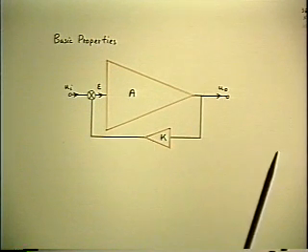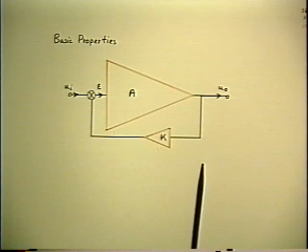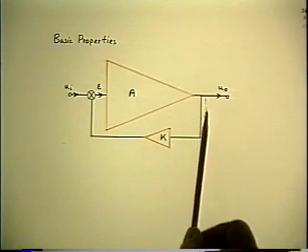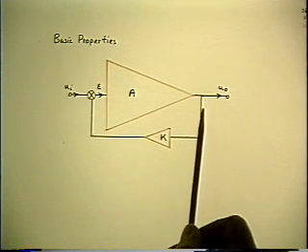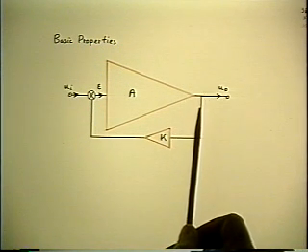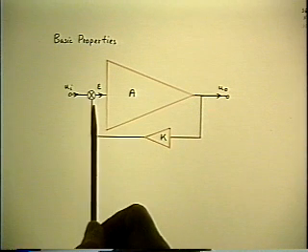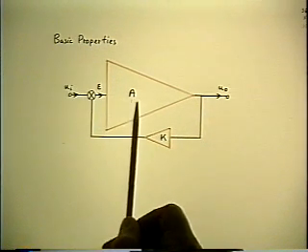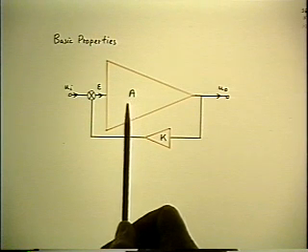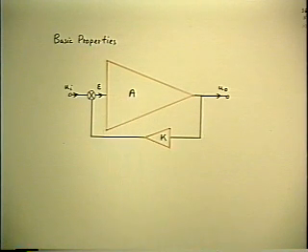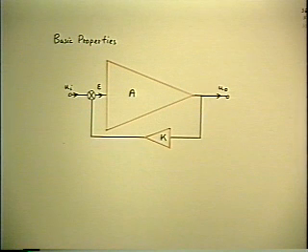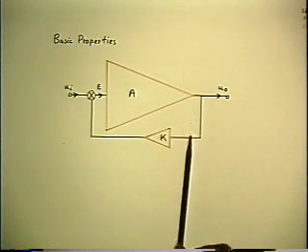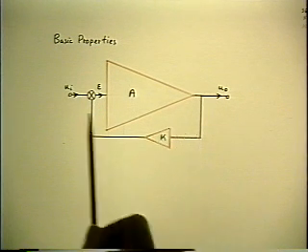If they are, it's easy, which in very many mechanical systems is true. You have a mechanical plant, and you have some sort of sensor which provides negligible loading on the output, and the fed back signal is subtracted from the input in a separate device which doesn't interact with the front end of the plant either. So in that case, the block diagram is realistic. But in many electronic circuits, it's not realistic because of interaction between the two boxes at both ends.